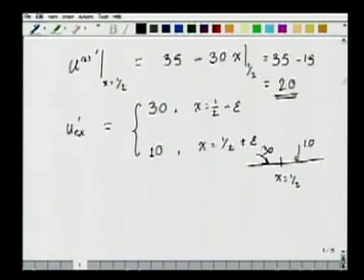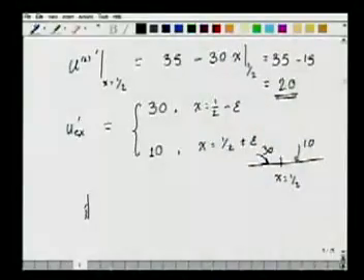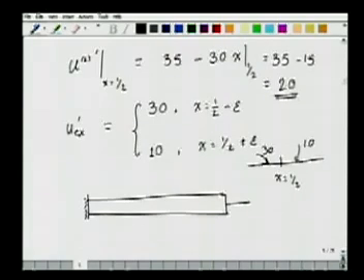Now, are these problems of interest to us, or are these simply artifacts that are created to show that the Rayleigh-Ritz method does not function? Unfortunately, most of the engineering problems that we are interested in do have this kind of a feature. For example, I may have a very general problem of a bar with multiple concentrated loads coming due to fixtures which may be attached to this bar. So I may have a concentrated load F1 here, F2 here, F3 here.